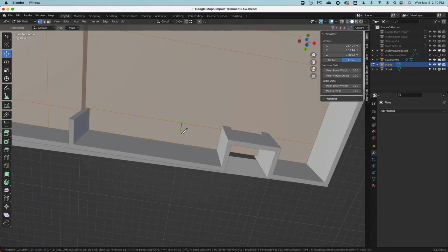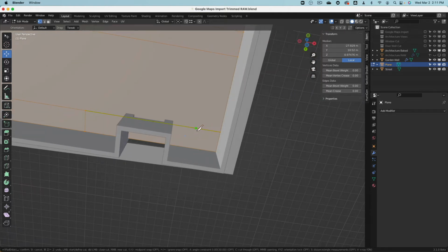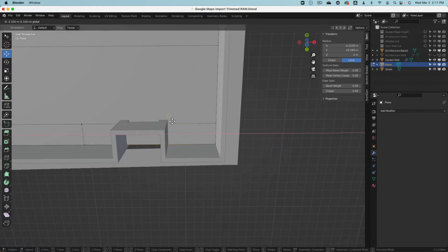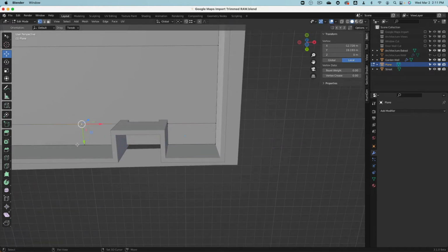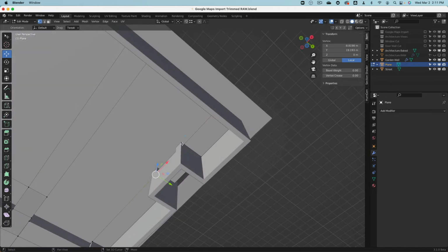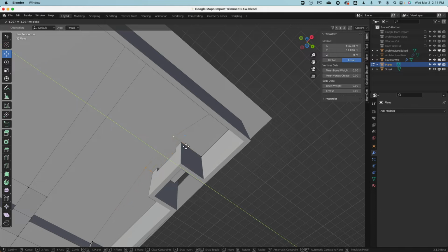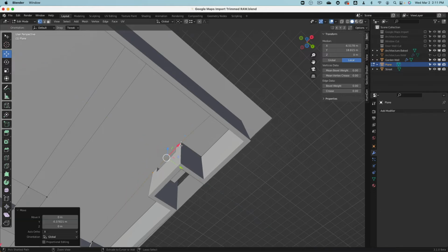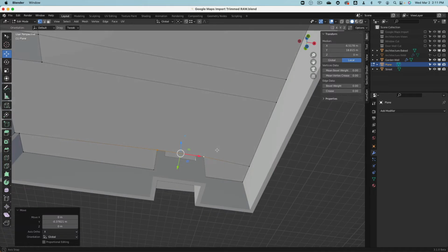K. Click, and then you see the K is like a knife, and I can, if I press X or Y, I can go along certain directions. Click. K one more time. Click and Y. This is the Y direction. Click on this other edge and enter. Now these 2 points, I can move, hold control and snap, as you can see, to there. This point and this point I will select and move a little bit back, hold control there. Thank you.